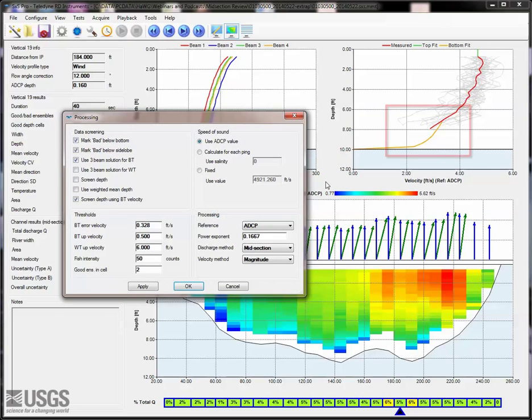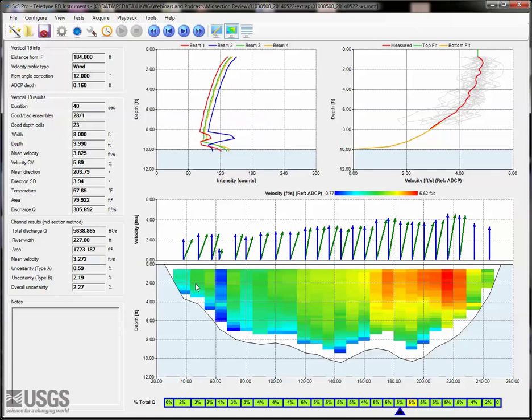In this example, we see that constant no-slip with the standard exponent doesn't define the shape of the measured data very well, but an exponent closer to 0.39 shows a much more reasonable shape, as would be expected in a cross-section with rougher than typical bed.